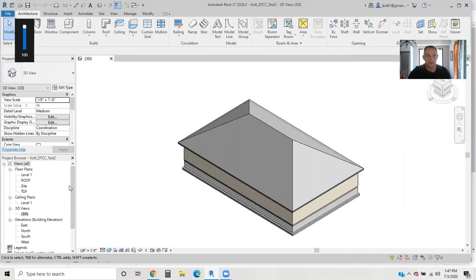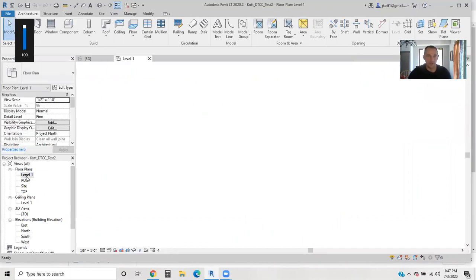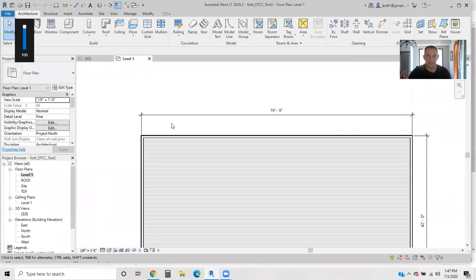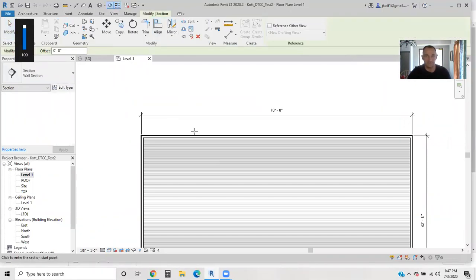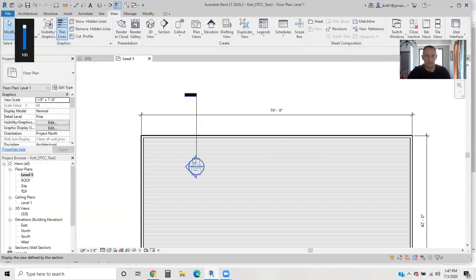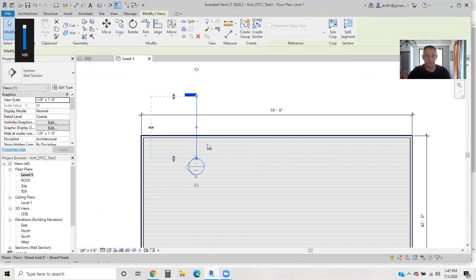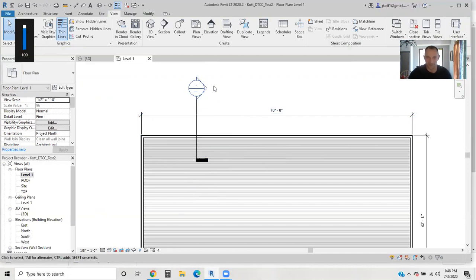All right. Now we're going to get started with the actual work of the test. To create a wall section, we come into the view area, click the section tab, and we draw that section. Now, this would be a section facing this direction. What we really want is a section facing the other direction so that it matches the example. And if you wanted to, you could switch the marker so that it would be at the top by clicking those 2 revolving arrows. You could switch the bottom marker. This is more of a conventional drawing standard.